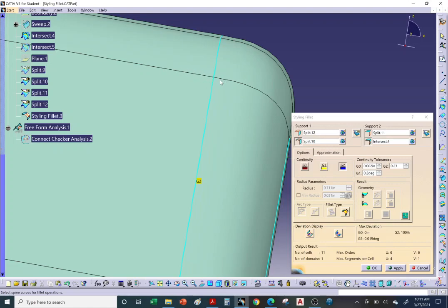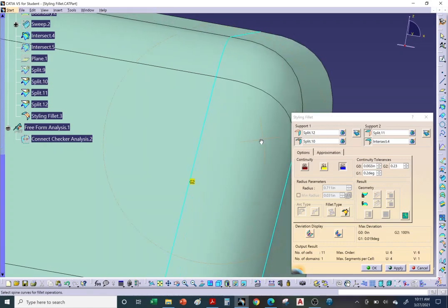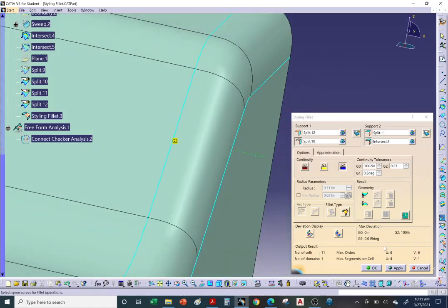So that's why it's trying to duplicate it as you exit. It's trying to duplicate this radius that goes on forever. And then it starts rounding off, right? So now the radius drops from infinity down to like 1,000, 100 inches, 10 inches, 5 inches, and 0.5 inches, and increases again. Okay. All right, so that's G2, and hit OK.